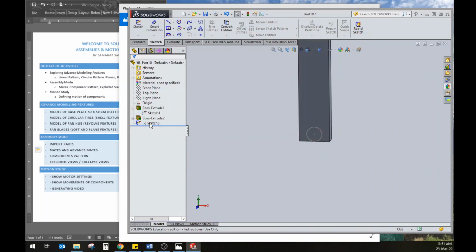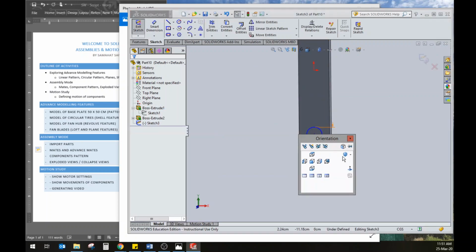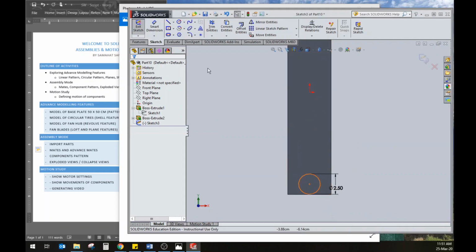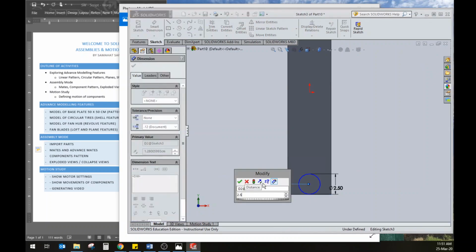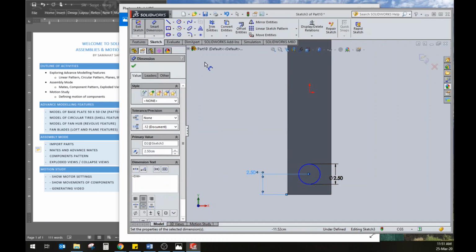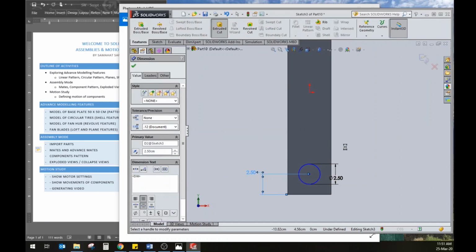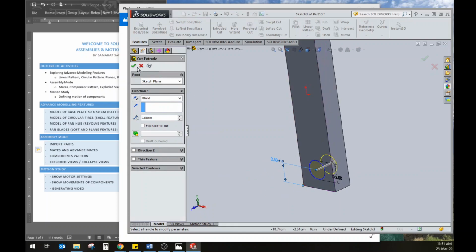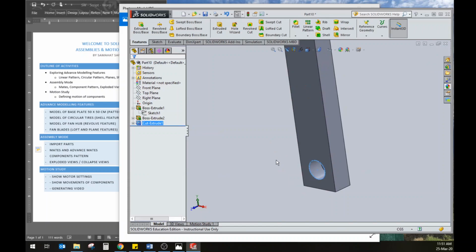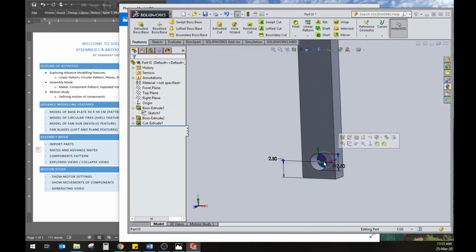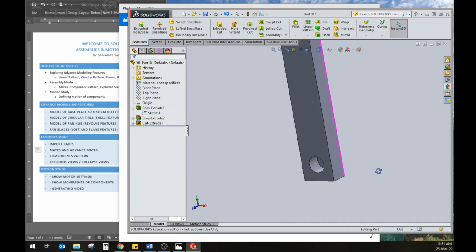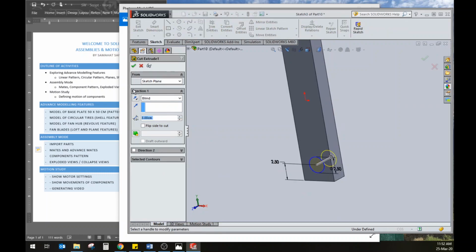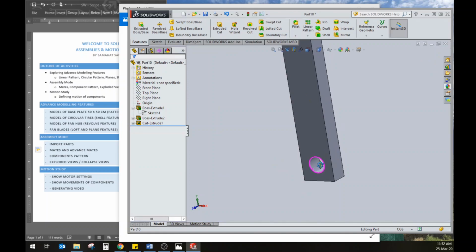Now the hole is coming in nicely, but I need to position it properly. So I'll click on sketch 3, edit, and make it normal too. And here my hole, let's give it a distance from here to here of around, again, 2.5. And it's nicely in the center. So just click on features, extrude cut. It should cut the hole inside this lever and click OK. Now in order to make things smooth, it didn't cut it inside fully. We need to give it a little bit more cutting depth. So right click on extrude cut, edit the feature and increase it by 1 more centimeter to check if it is cutting fully. Yes, good.